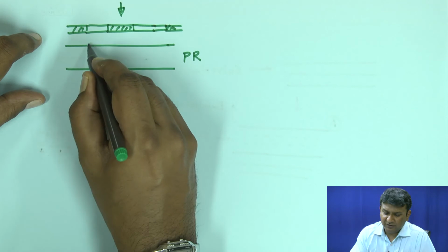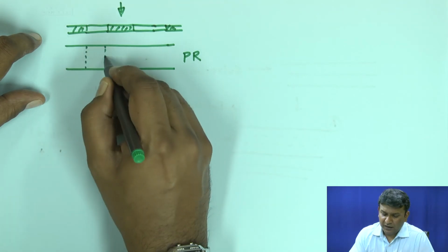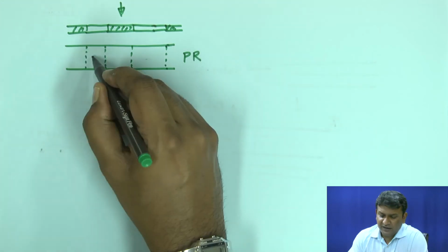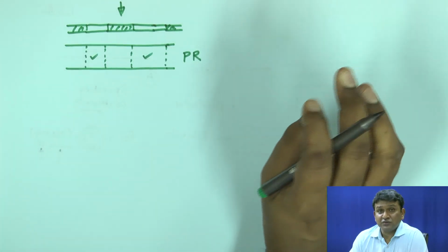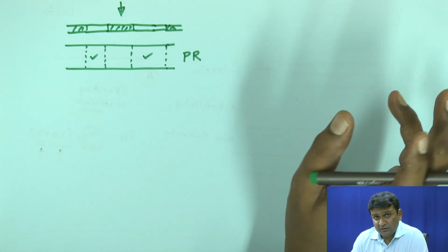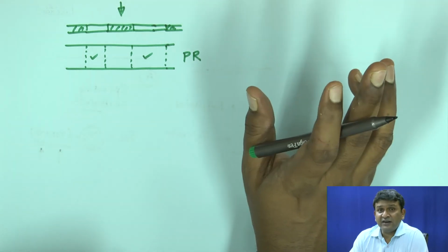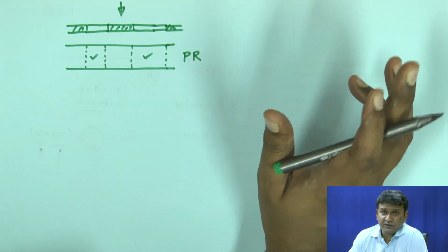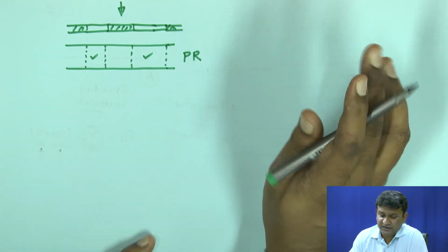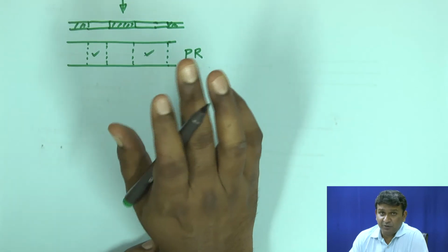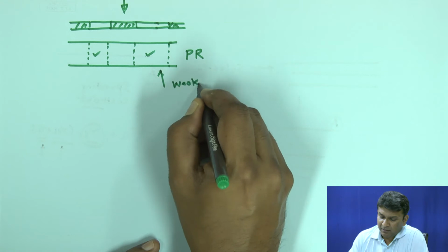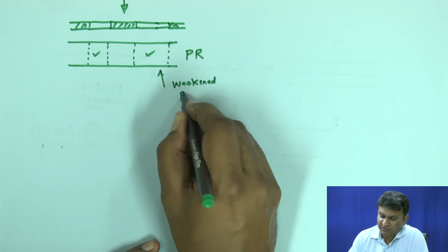It is also acting as a good revision for all of you, and what you have is these areas have been exposed to light, right. So now you need to worry whether they have hardened or they have degraded, that depends on whether you have a negative photoresist or a positive photoresist, but whatever it is, these areas have changed their properties. Let us say these areas have weakened. So that means we actually have a positive photoresist.